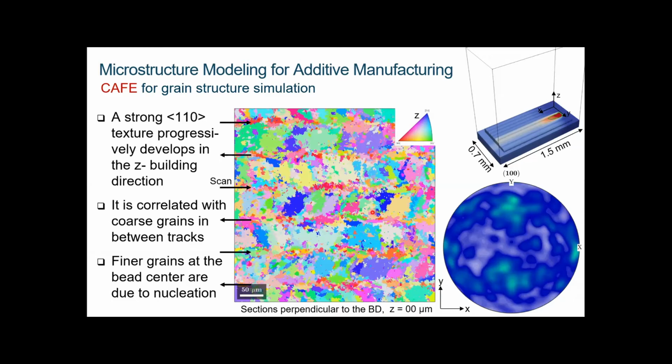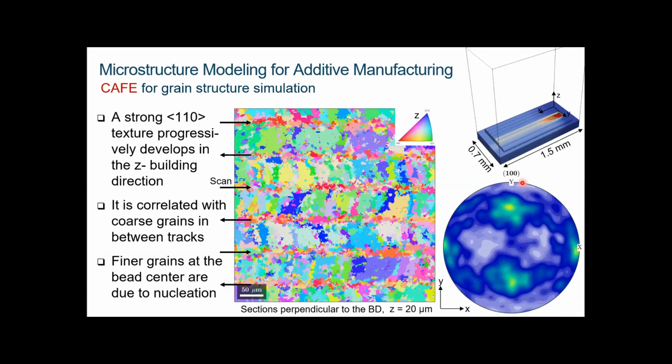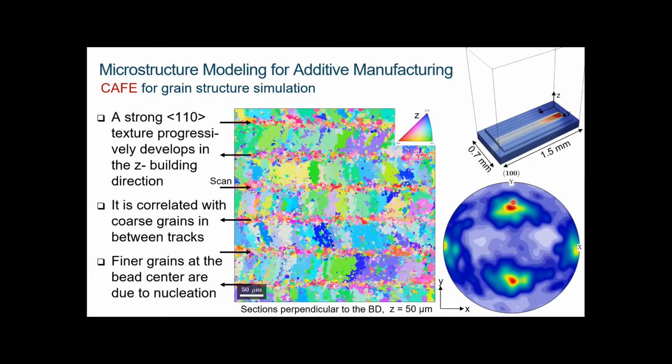This is one of the pole figures. What you will see when you are at the very top of these images here that I have put together, so at plus 50 micrometer in the third layer, you can see that you have two strong 1,0,0 directions along plus z, which is at the center of the pole figure, plus z plus y and plus z minus y, meaning that the 1,0,0 main dendritic growth directions are actually 45 degrees away from the construction direction, the z direction, toward the transverse direction plus y or minus y.